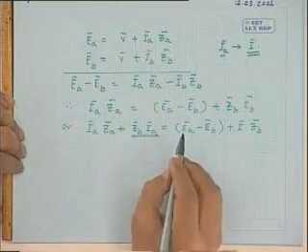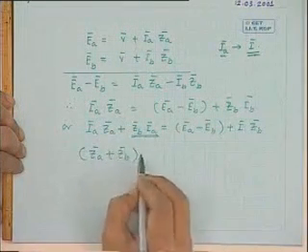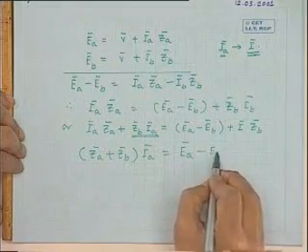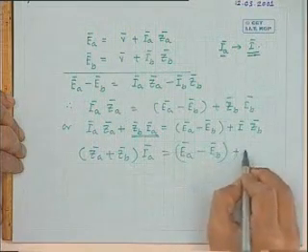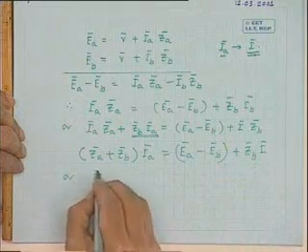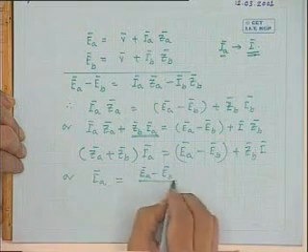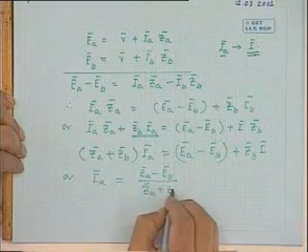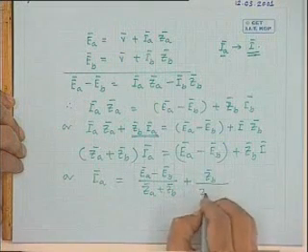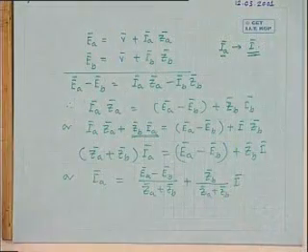That is, add this term to both sides, so that on the left hand side it will be ZA bar plus ZB bar into IA bar, equal to this one. Or IA bar will be equal to EA bar minus EB bar over ZA bar plus ZB bar, plus ZB bar by ZA bar plus ZB bar into I bar.